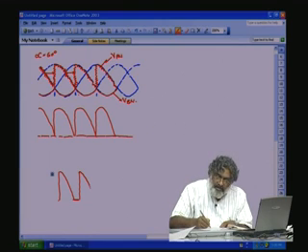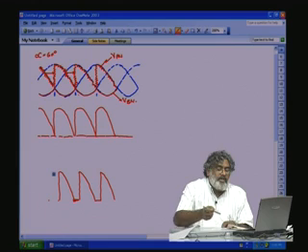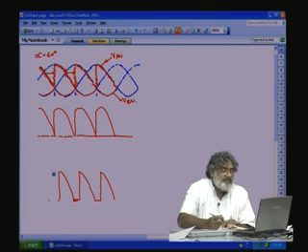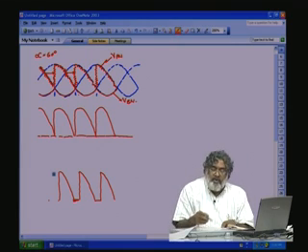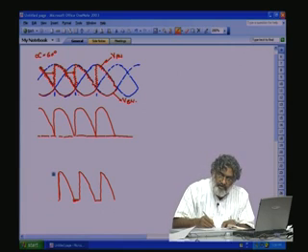It will come here. So as the firing angle increases, slowly the discontinuation period will increase and the output voltage will come to 0. So the equation for the output using thyristor and diode, as I told you, is Ed0 into (1 plus cos alpha) for the semi-controlled converter. Okay. So it will come like this.